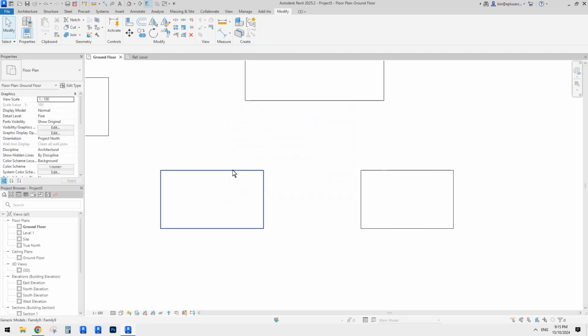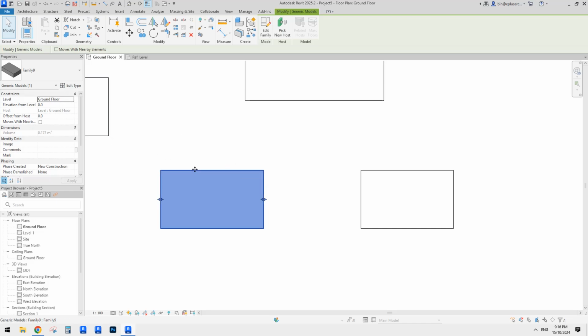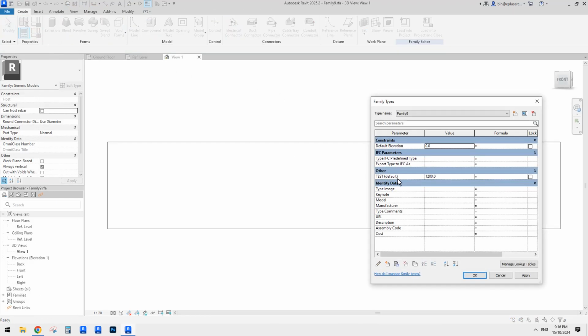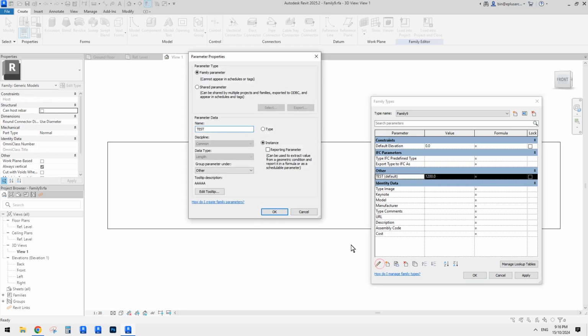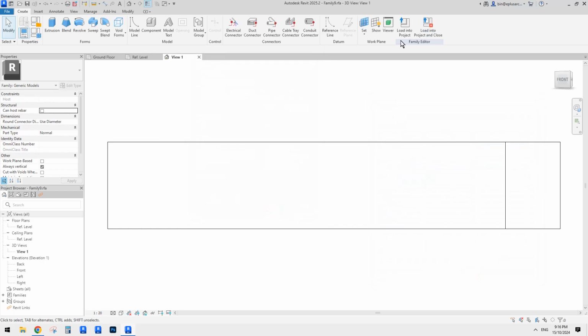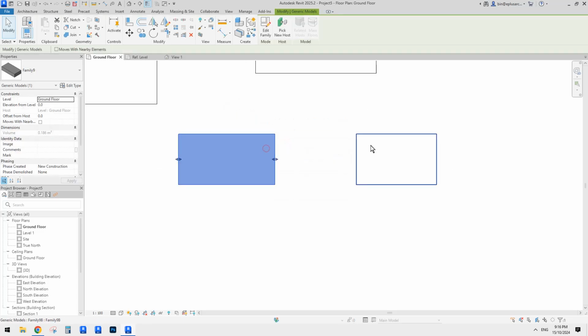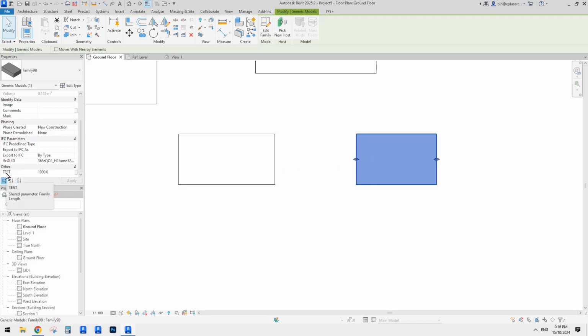And now we also need to apply that shared parameter to family 9. Edit family, go to family types, select test, edit, same, select test. OK, OK. Now load this one into the project as well, and override. Now these two families share this parameter, so they are the same.